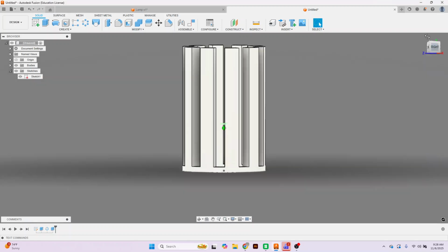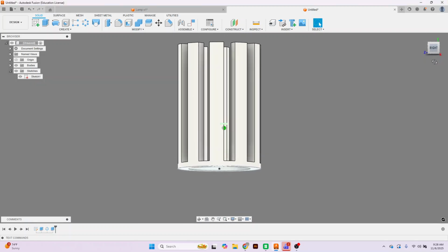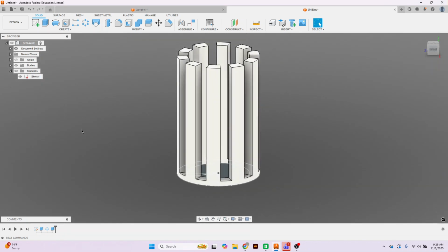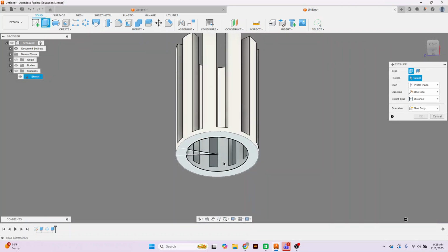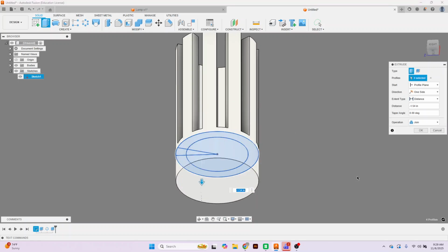I still want my sketch to show because this last part, I'm going to extrude the top, and I'm going to do something that is new. When I click extrude, I'm going to select the whole thing. I want all of my pieces to be selected. But before, whenever you extrude, you would extrude off of wherever the sketch was drawn. We're going to change that.